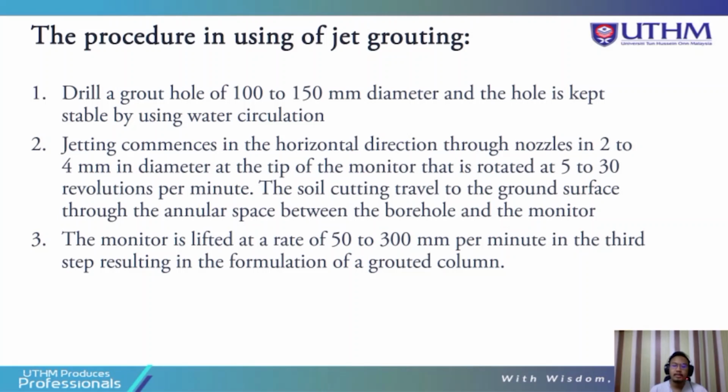The soil cuttings travel to the ground surface through the annular space between the borehole and the monitor. And lastly, the monitor is lifted at a rate of 50 to 300 mm per minute in the third step, resulting in the formation of a grouted column.